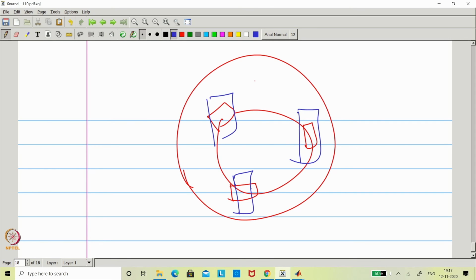So in the sense all the wheels are aligned in that direction. This would have two inputs: one input for the drive, and the other input to orient all the wheels in the same direction of orientation. This is very close to the rotating chair. When you drag the chair, you can see by looking at the bottom that all the wheels are aligned in the direction in which you are applying the force.